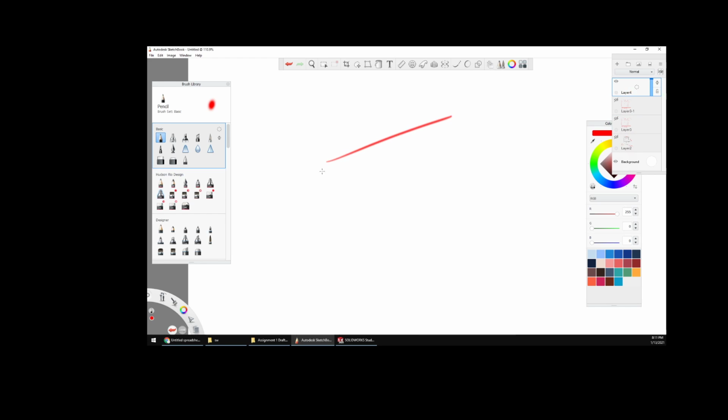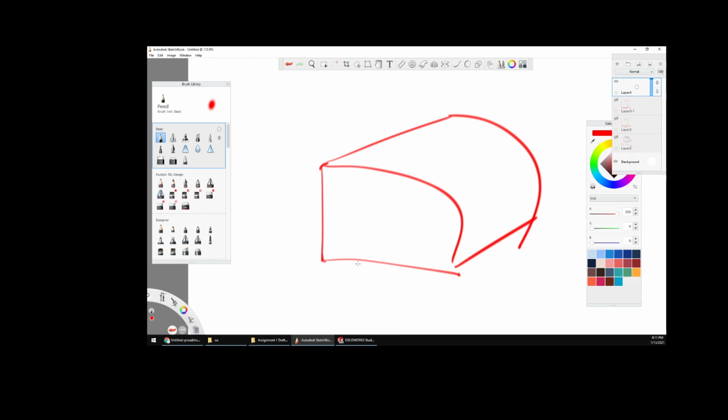Thornton told us about typical. Did he? Yeah. Okay. So basically, if I call out typical here, that means unless there's a dimension on a different radius, this would be 0.5, this would be 0.5, that's the assumption, unless I put another dimension up here, and that's 0.65. But anything else, 0.5, 0.5, 0.5, that's what it means. So unless I call out a separate dimension, assume it's all 0.5. The dangerous thing about that is if you miss one that isn't.